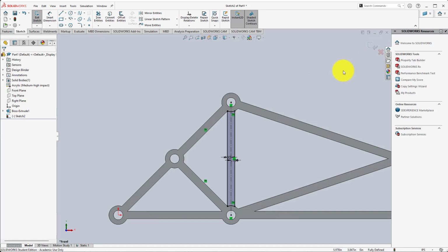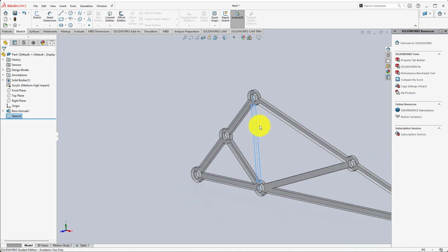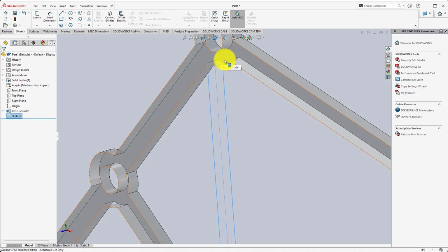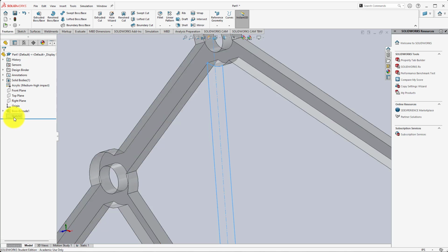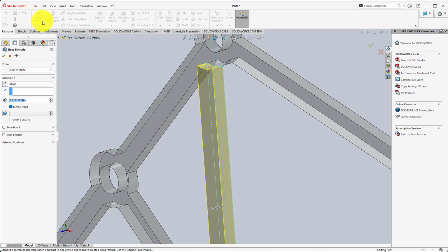So we now have this sketch ready to go. And I drew this intentionally on this face. When I drew my main extrusion, I drew it on the back side and extruded it upwards, going up positive Z. So when I did this sketch, I'm going to have to extrude it negatively into the part. I'm going to hit extrude. When I extrude this, you notice it's coming out the wrong direction, so I can flip the direction.